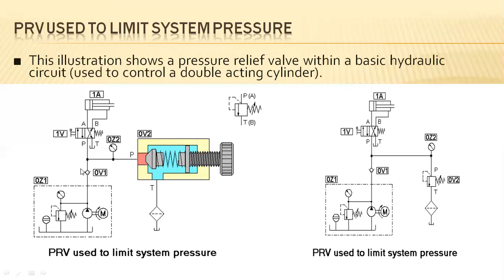Sorry, not the DCV, this is the check valve. The check valve plays a major important role, in that it doesn't allow the fluid to flow backward. So if the motor has been switched off, not even 1 bar of fluid will be entering into the circuit design. So continuous supply should exist, but limiting the pressure after crossing this check valve is impossible by this particular unit, to decrease the pressure which is already in the fluid.